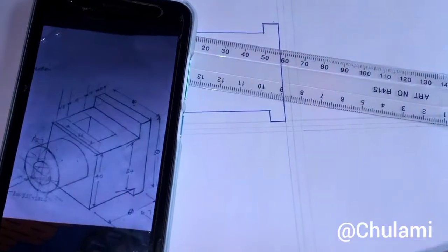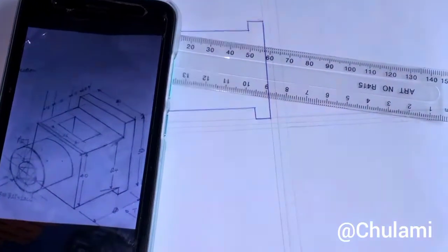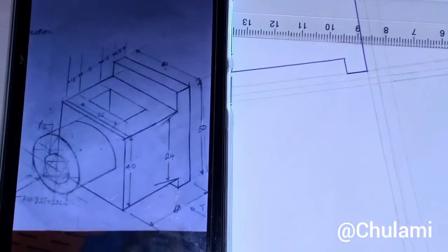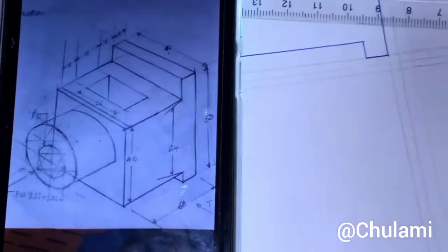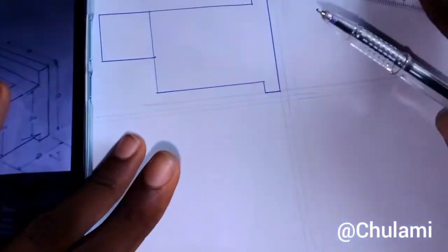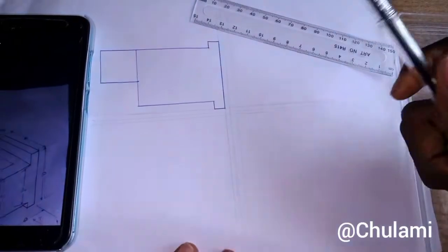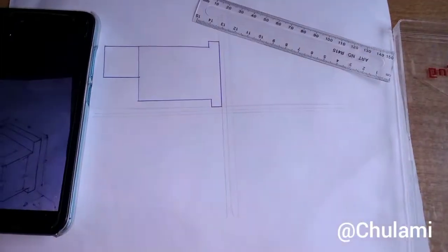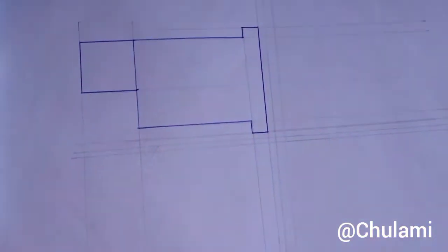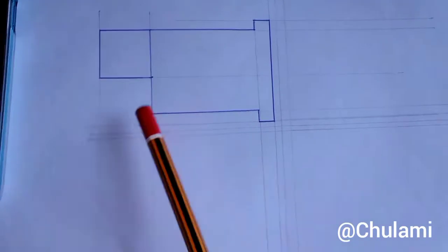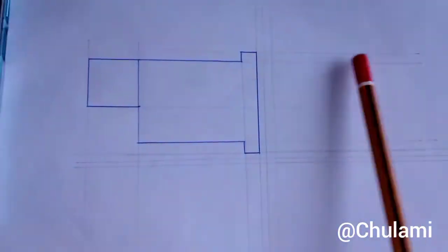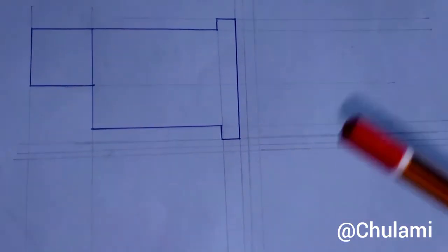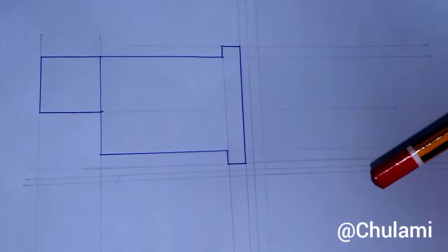Okay, look at it from this perspective. Now let's go to our side view. But let me tell you something. In this kind of isometric block, we project lines to guide us after drawing other parts. That's why I prefer that we draw the front view first. With this front view, we can get an idea of how the other views will look. So let's draw. Okay, now if you watch, I've projected all the lines. These projected lines will help keep me on a safe and smooth path, to make sure that all parts align, because if you assemble all these parts, you make up this isometric block.